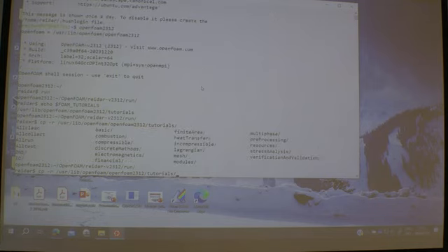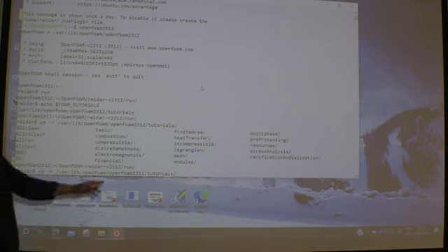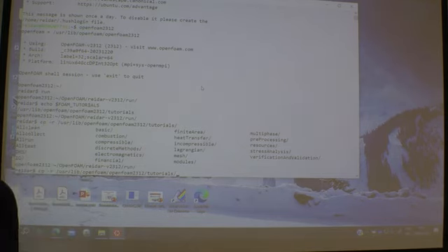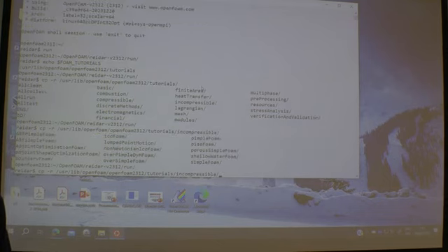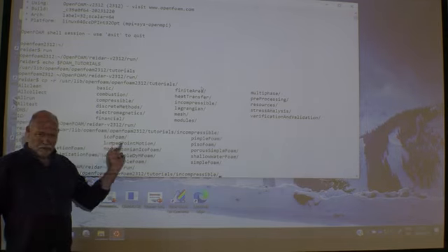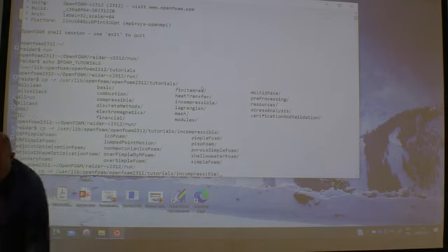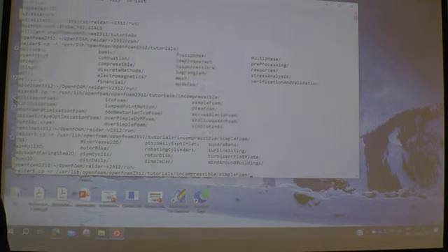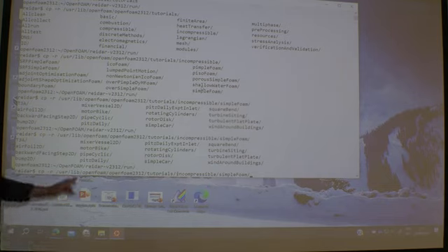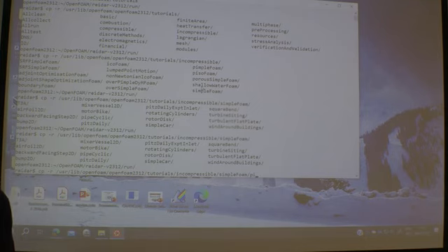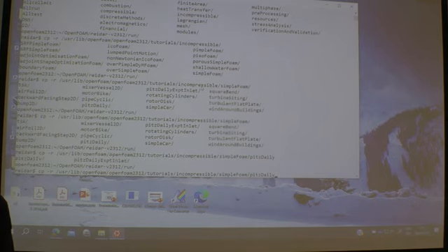Under tutorials, I find it under incompressible, and under incompressible, I will now have a program, not icoFoam, that was what we used when it was laminar. You use simpleFoam. Under simpleFoam, you will then find the pitzDaily case. So let's have a look at that one. pitzDaily, and under pitzDaily, we actually have another pitzDaily.